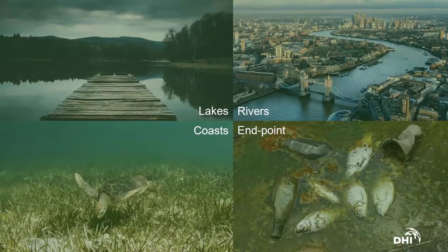And then climate is important. Most biological processes are influenced by water temperatures, and many models use an Arrhenius or an exponential temperature expression. So if you are using a model developed for temperate waters in a tropical environment, then you can really speed up processes undesirably. So that's just a small remark.